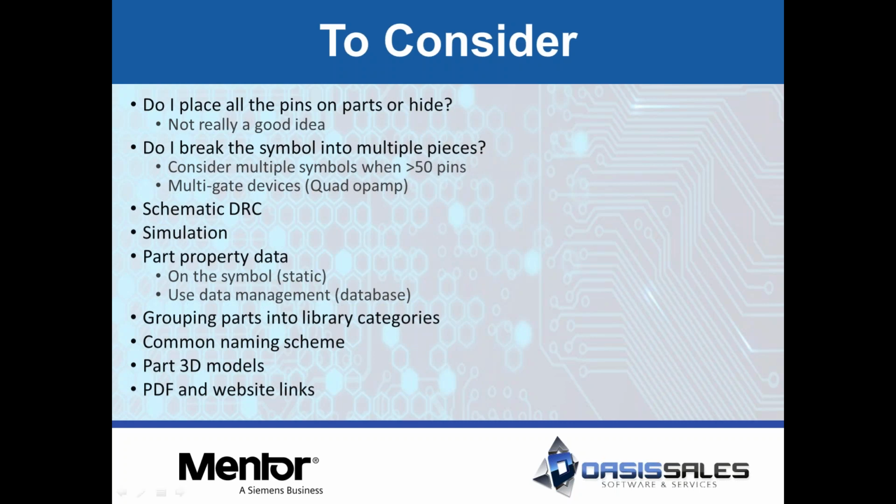So use things like signal integrity tools and analog simulation products, power analysis tools. They're all available out there. If you're a PADS Standard Plus customer, you have some of this stuff right at your fingertips. I talked about this in our last webinar with doing basic signal integrity. But you need to put properties on your parts to make the whole process of using those simulation tools, again, easy. And that's where adding that information onto your schematics or your library content will just save you time.